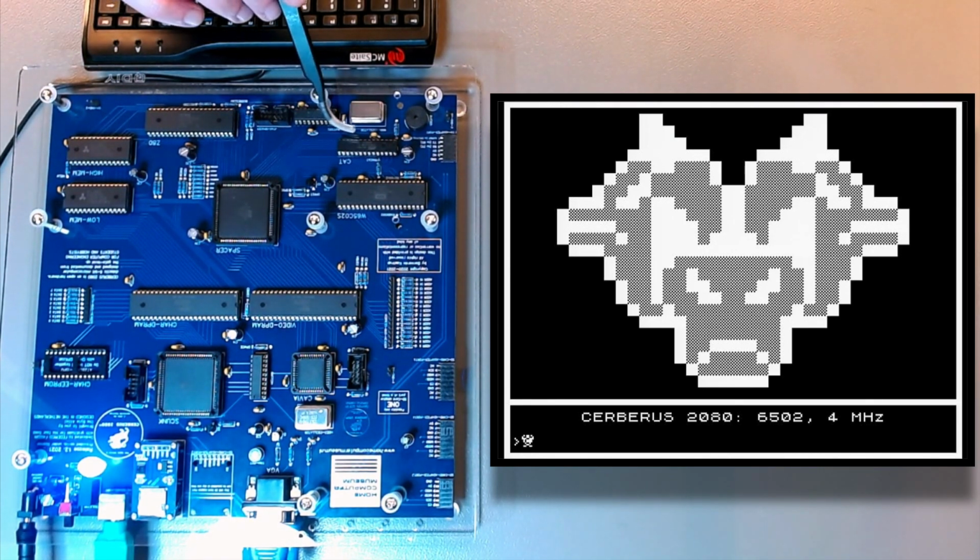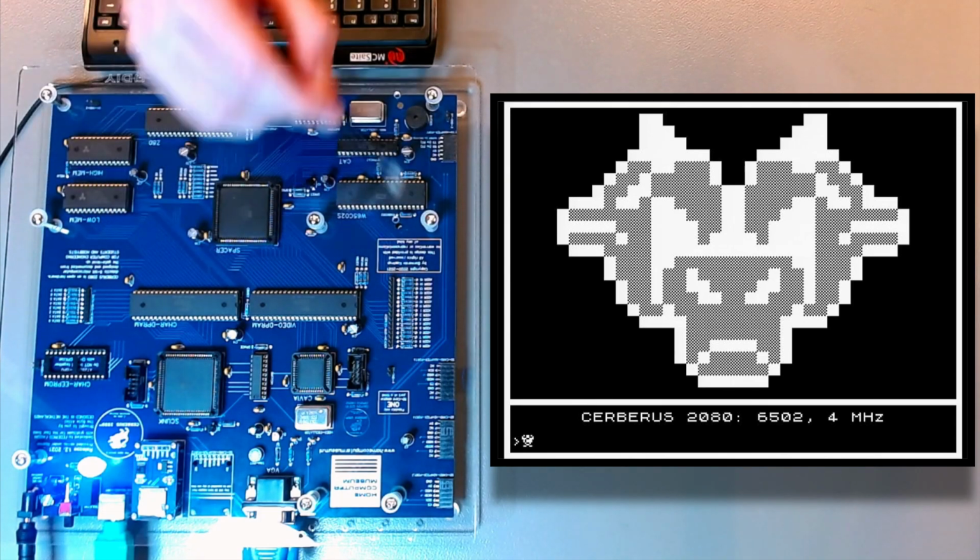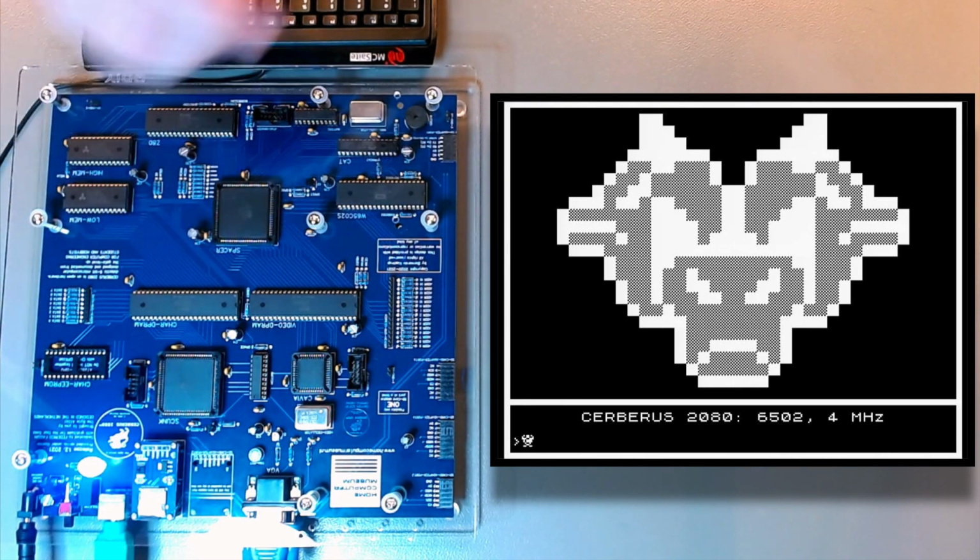We also have an I/O controller, which is an Atmel ATmega328, the same chip that is in the Arduino Uno. This is also just a buffer, like this one, to strengthen the signals. This is the 16 megahertz clock that governs the computer proper here on the lower part.